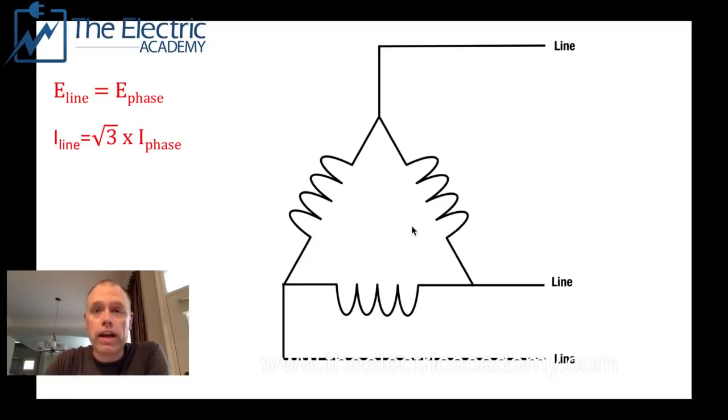Anybody that's worked in a plant knows that you have a ground fault detection system that just indicates which phase it's on. Then you've got to go looking for it. I've done that. I've spent days trying to track down ground faults in a plant that I worked at, a styrofoam manufacturing plant, in fact. What else? They're really useful for distribution for that reason, because you have 3 wires, not 4, so you save some money on that. Let's just see if I've covered all my notes here.